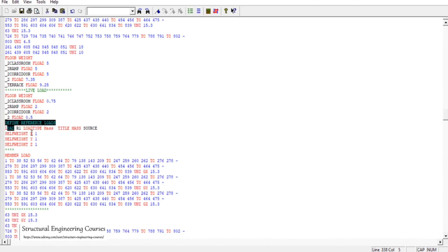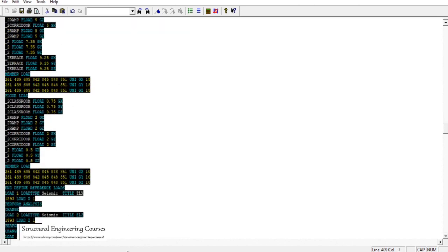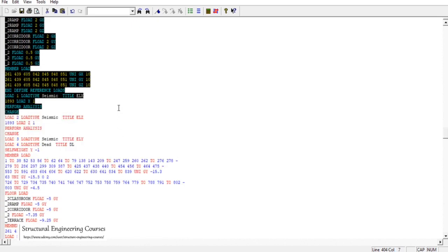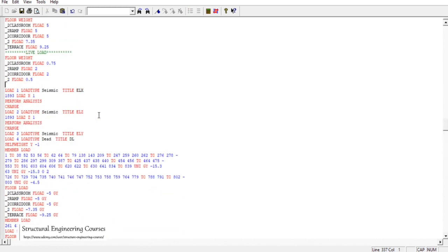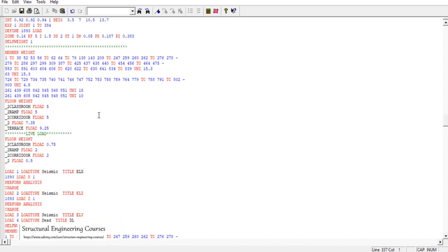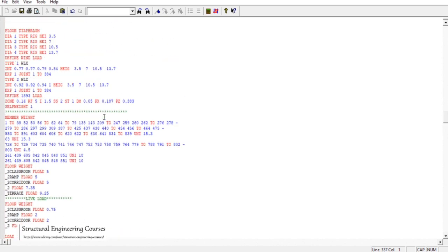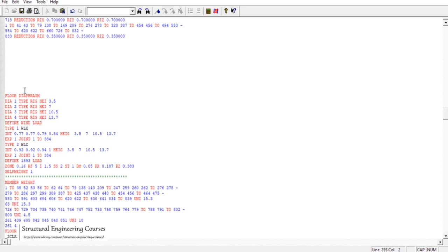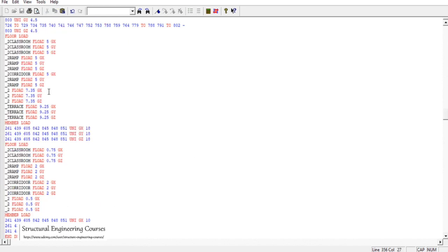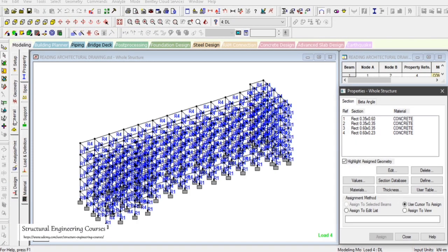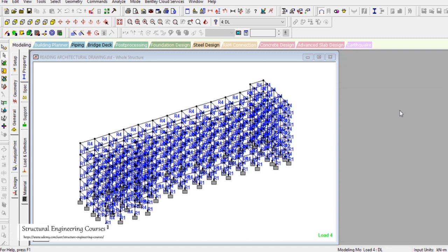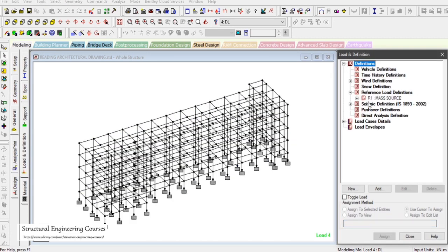So we select the option from define reference loads here, and cut all these commands by pressing Ctrl plus X on my keyboard. Then we go to this space here, that is before floor diaphragm, press Ctrl V on the keyboard and save the editor file. Now we can see that the reference loads are still available here, so that is not an issue.